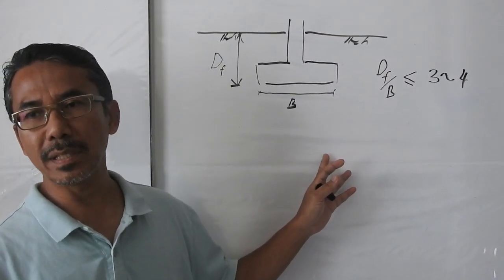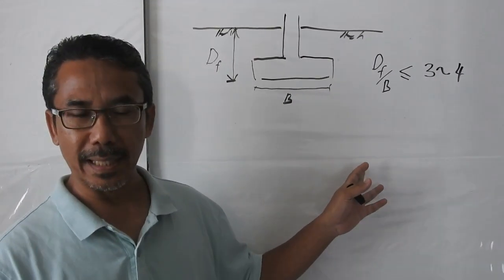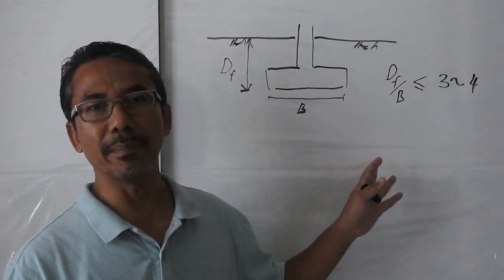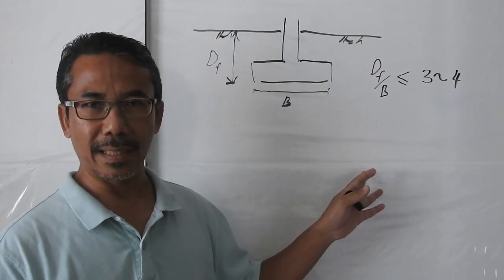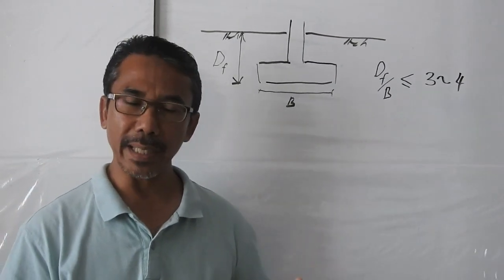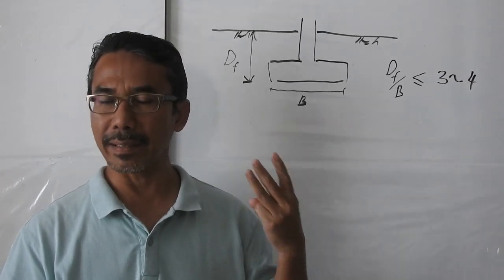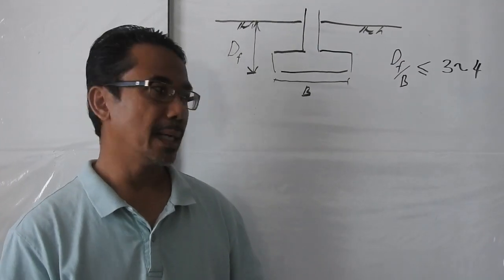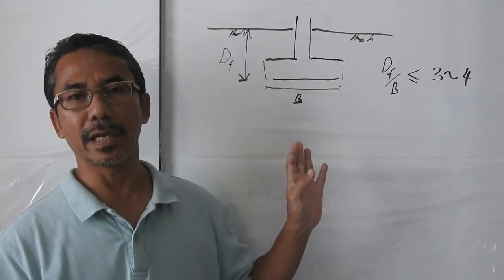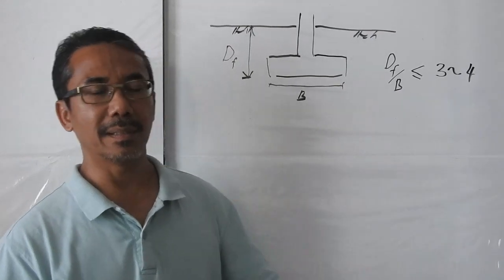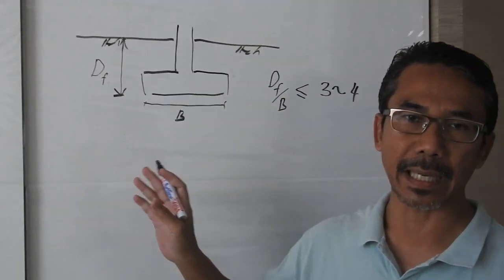Second equation is to be used in calculating the bearing capacity of a rectangular footing. And another equation that can be used to calculate bearing capacity using Terzaghi's equation is for circular footing. So, as a summary, we can use 3 different equations based on Terzaghi's theory depending upon the shape of the footing. Another equation that can be used to calculate bearing capacity of shallow foundation is Meyerhof-Hansen's equation. Right. So in this session, let me talk about Terzaghi's bearing capacity equation.